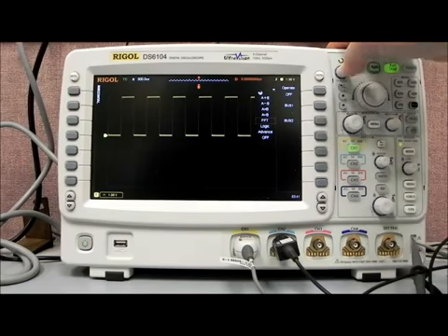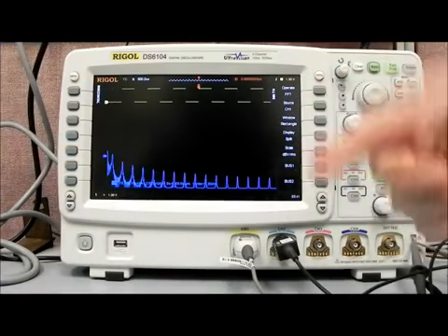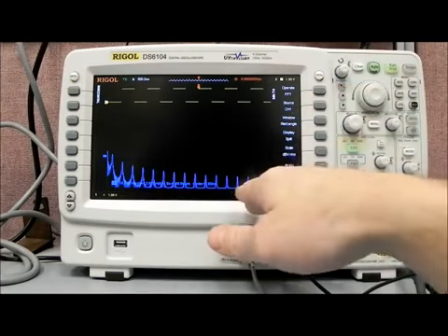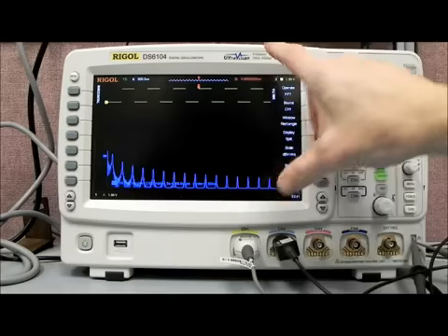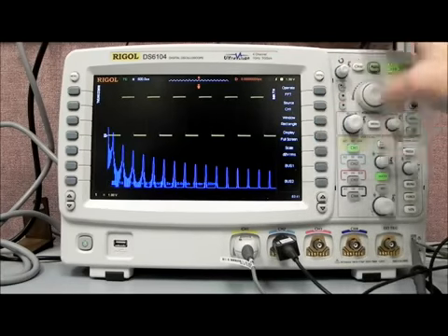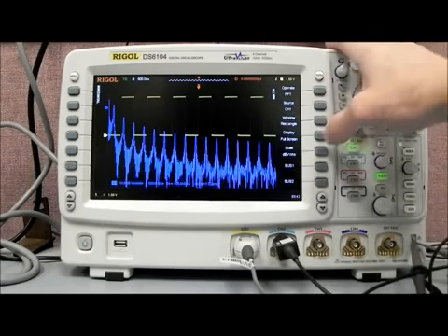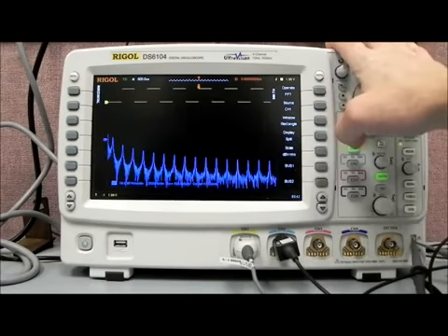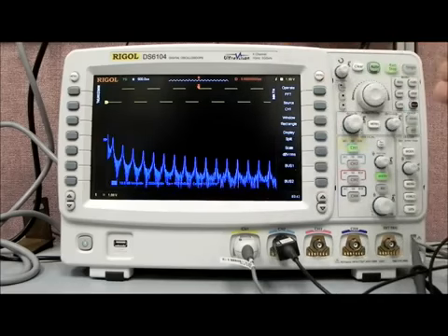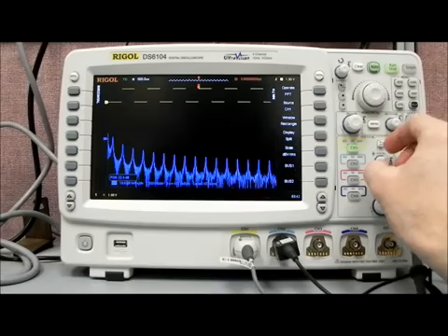Let's cover that. And with the FFT, we're actually taking the time domain signal up above, and we're processing it and pulling it back into the frequency domain. You'll see now we have a split screen, which we can go from a split screen to a full screen if we'd like, and we can then manipulate the position of the FFT on the full screen, or we can go back to split screen. Personally, I like to have a split screen because they really are just different scales.